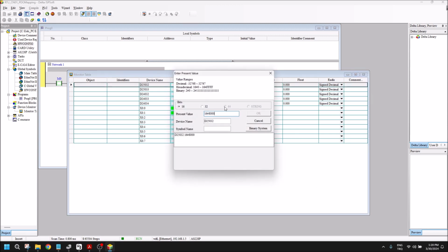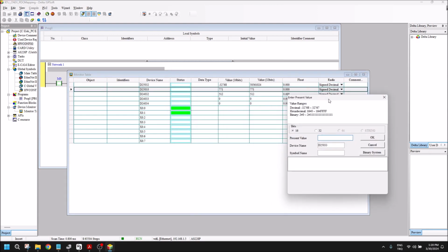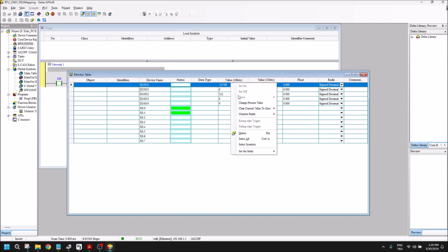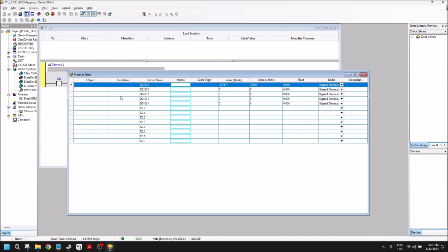I will stop my RTU. So when I change my output value, there will be no change for output part. So let's clear outputs. You see here my data changed into 0, but the module still same. So I will put here 8001. When I enter this value, 0 will be sent to the RTU, then my output will be clear. So when I enter, you see here output has removed. So this is one way to use